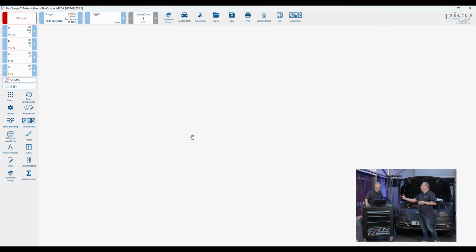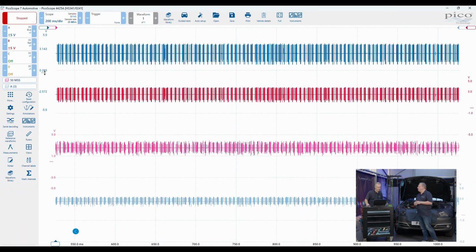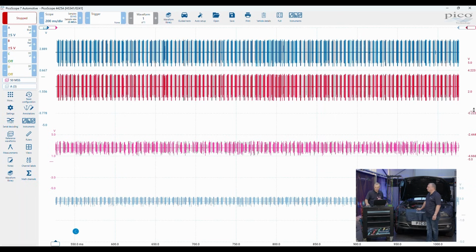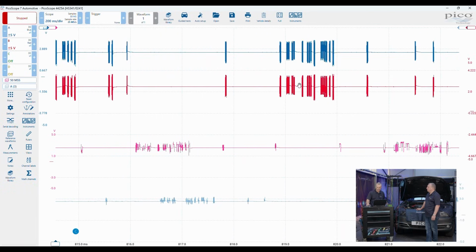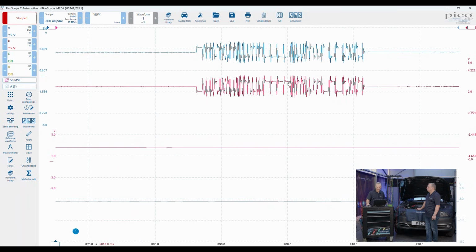So we're now measuring, we've added, because it's a twisted pair differential bus, we've now added the second measurement, which is bus minus. Yeah. I don't know whether the camera picked it up there, but the second I added a second probe, the dashboard chimed, and no doubt we have intruded onto the network. The network itself has recognized that there is some kind of intrusion is the only word, really. There's a foreign object on the bus. On the bus, yeah, something that should not be there.